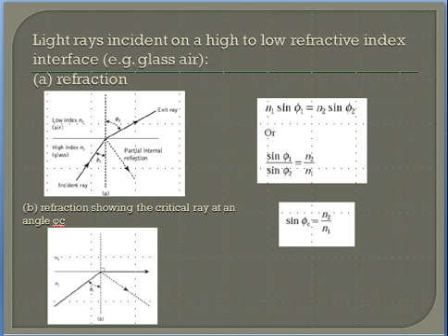At angles of incidence greater than the critical angle, the light is completely reflected back into the originating dielectric medium with a high efficiency of around 99.9%. Hence, it may be observed that total internal reflection occurs at the interface between two dielectrics of differing refractive indices when the light is incident on the dielectric of lower index from the dielectric of higher index, and the angle of incidence of the ray exceeds the critical angle.